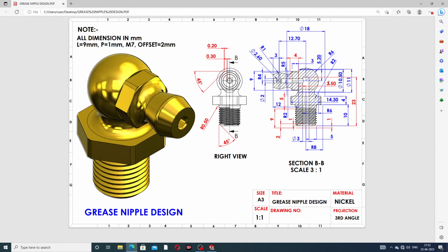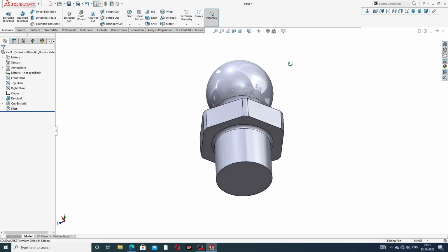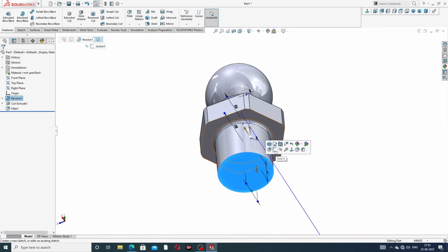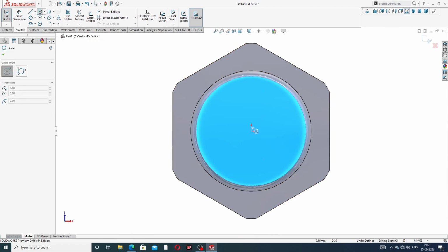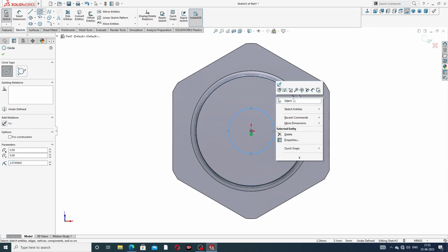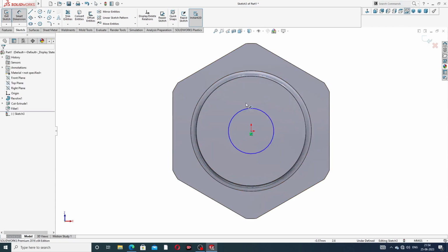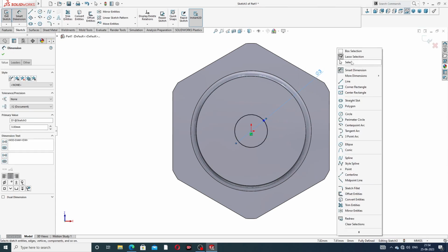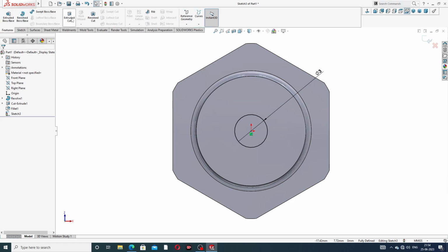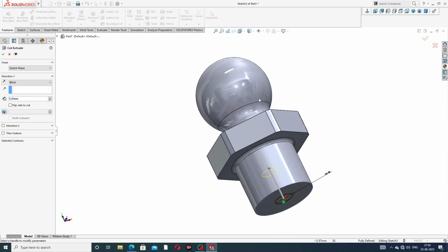3.5 millimeter is perfect, and one is also cutout, a 3 millimeter, and 23 millimeter is cutout. Also this face sketch normal, and drawing a circle. Circle is 3 millimeter, and this is perfect 3 millimeter, and this cutout is extrude cut. Extrude cut is up to 23 millimeter.